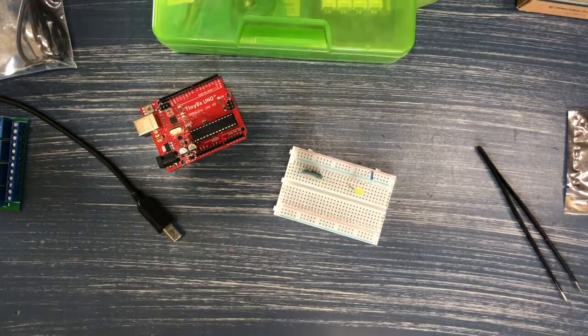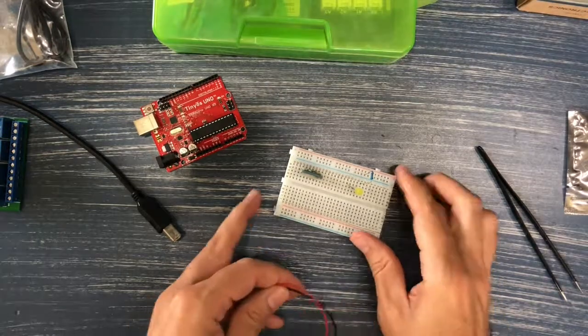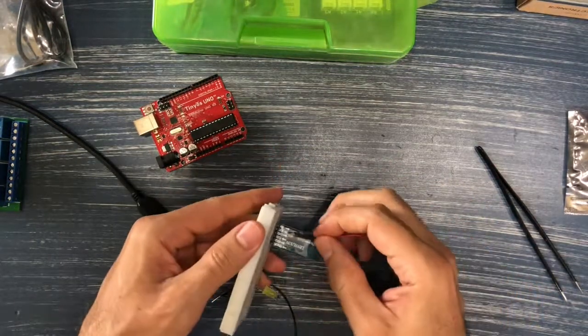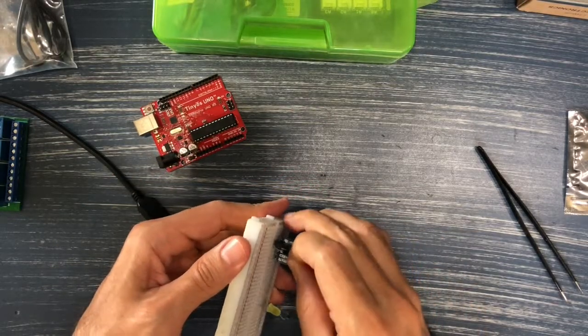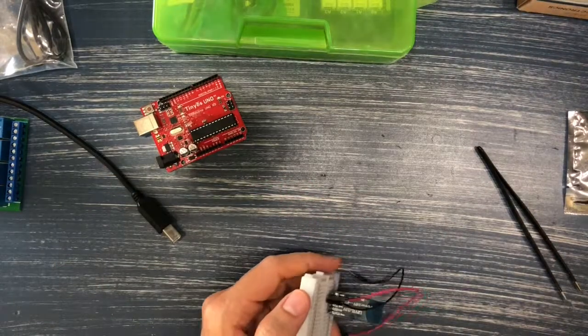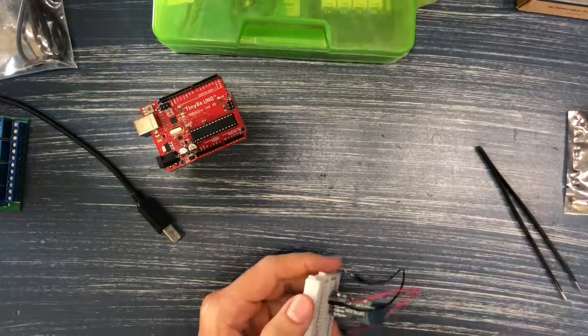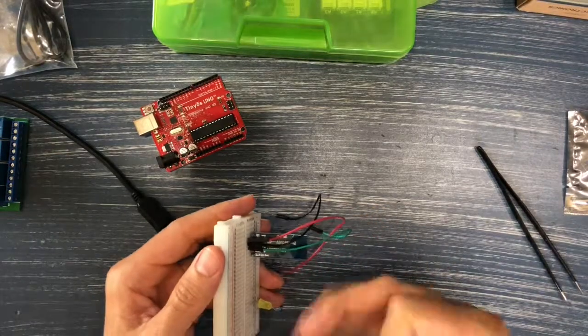Wi-Fi and Bluetooth and many of the radio and communications modules use an RX and a TX pin. The R is for receive and the T for transmit. This is important because it follows the same protocol. The VCC and the ground always go to the 5 volt in this case, and 0 volt ground.